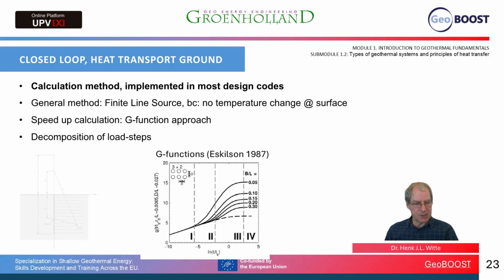On the left, we can see a line drawn in the ground volume, where on the line we have all kinds of points. We have point sources, and there is a well-known equation for the heat transfer around a point source. Integrating all the points on the line, adding them all up, will give us the solution for a line source, the finite line source equation.